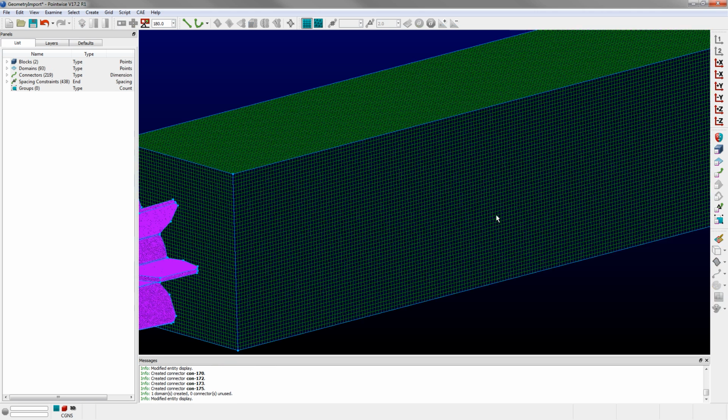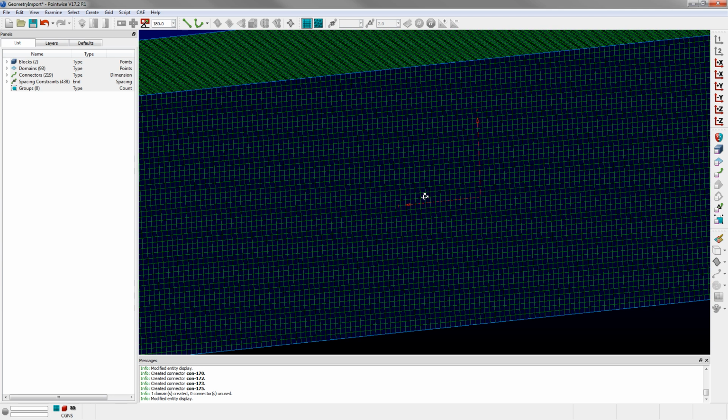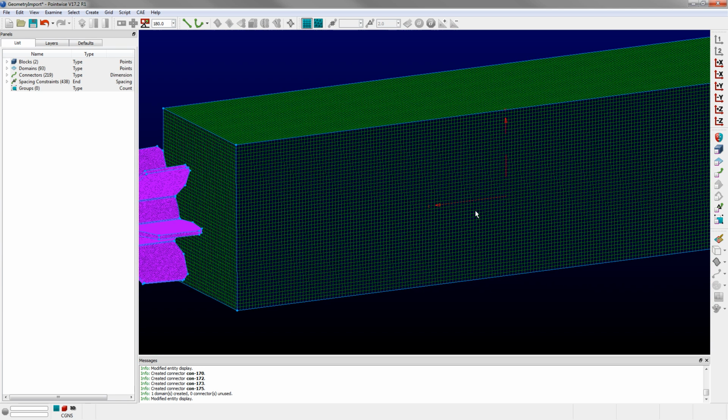and zoom in, you can see basically I have a nice uniform structured block. And why is it uniform? Well, it turns out that in order to interface with an unstructured block, a pyramid will have to be generated on the surface of each quad. Okay, and the more uniform that quad is, the higher quality that pyramid will be that's generated to transition between the two element types.